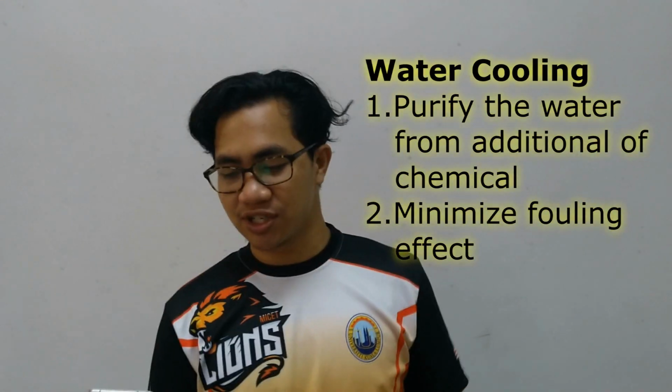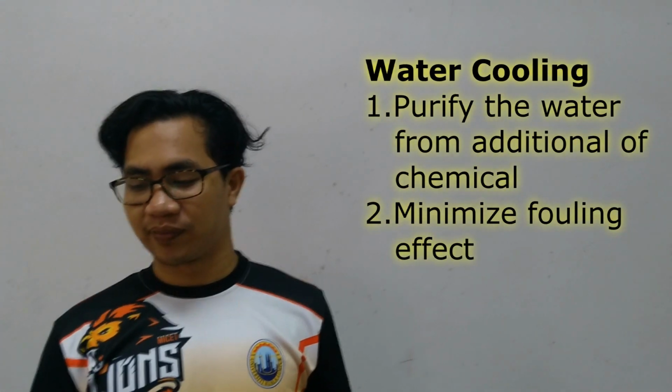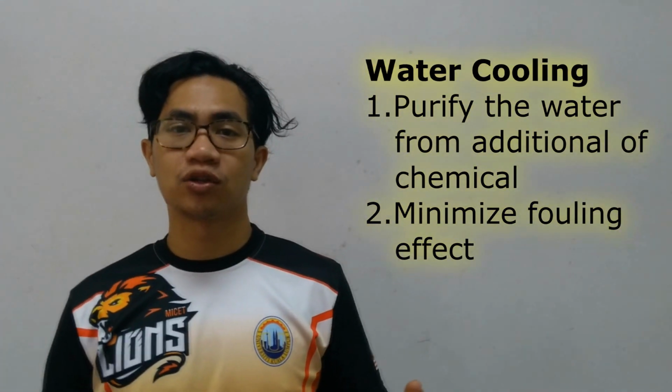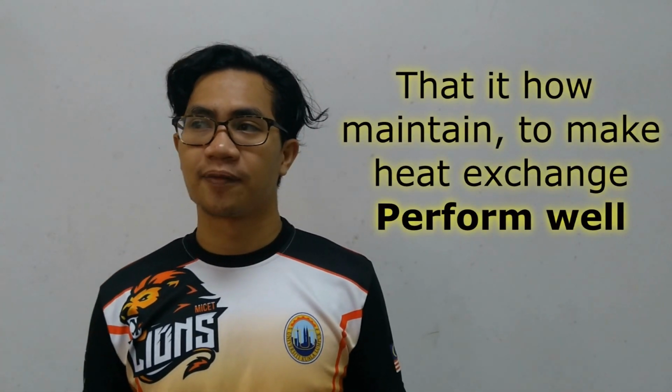For water cooling system, we need such as purification. We need to purify the water, addition of chemicals, and we will find a way to minimize the fouling of the heat exchanger equipment. For other water treatment also, we need to use steam system for power plant, etc. to minimize fouling and corrosion of the heat exchanger. So that's it. In short, that's how we maintain